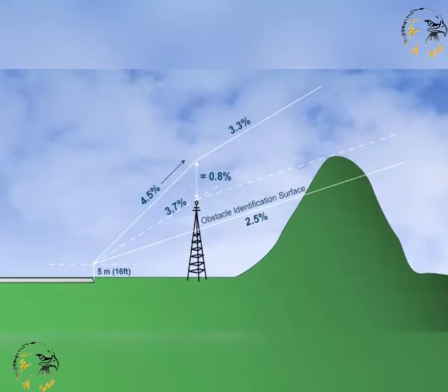In the turn initiation area, the minimum obstacle clearance of 295 foot is provided. Of course, in specific areas of more mountainous terrain, increased obstacle clearance will be afforded. If DME is available, additional height or distance information is made available. Mountainous terrain is not defined, but when designing departure procedures, if average wind speeds of more than 20 knots prevail and the terrain produces downdrafts, then increased obstacle clearance criteria are applied.